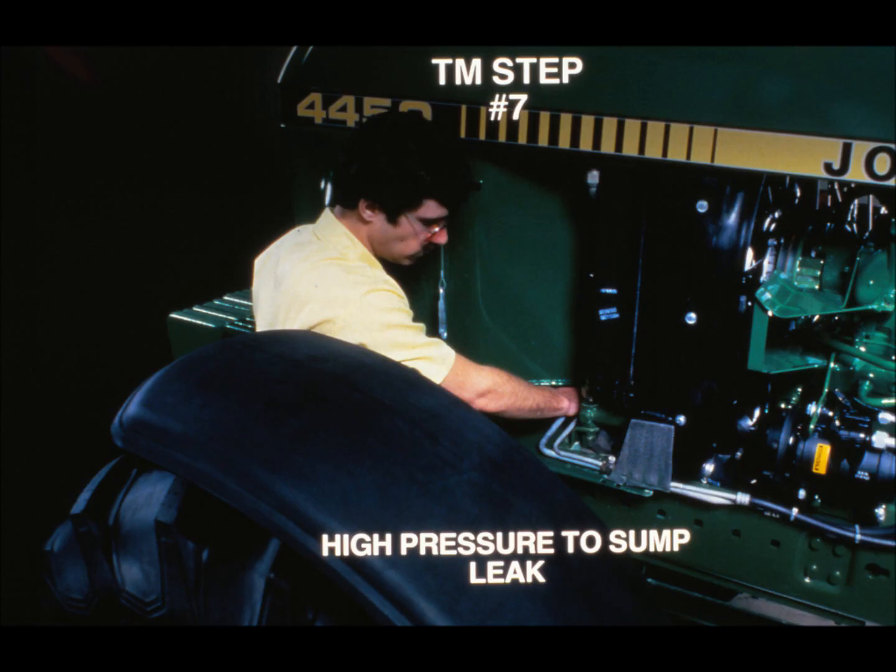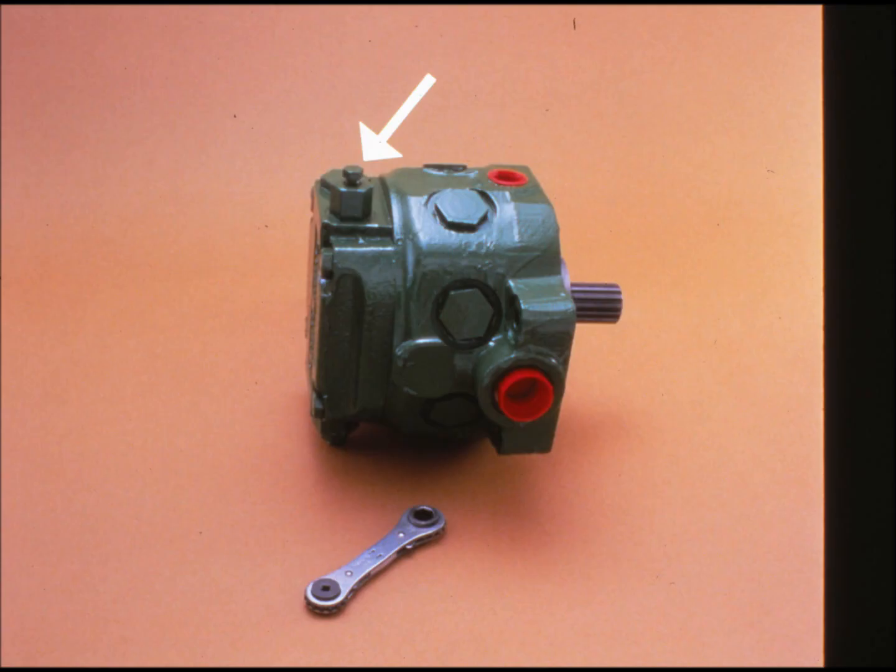Step number 7 is the first diagnostic test. This step checks for any high-pressure leaks to sump. To perform this test, run the engine at 1500 RPM and record the lube pressure before and after destroking the main hydraulic pump. On most tractors, this will require installation of a destroking screw. Some 50 series may already have a destroking screw. The ratchet wrench in the pressure test kit can be used for destroking the pump.